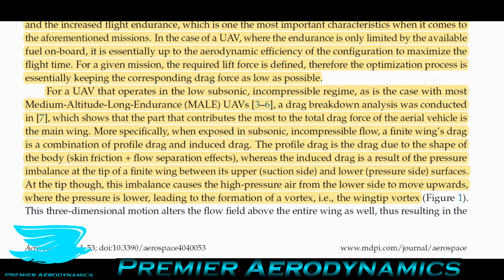So the skin friction is when the flow goes over a surface, there's some sort of resistive force between the fluid and the surface because the surface is bumpy. The pressure drag is anytime you have two surfaces, one front, one back, or they have some component of their area in that direction. The difference in the pressure on those two surfaces will create a resulting force.